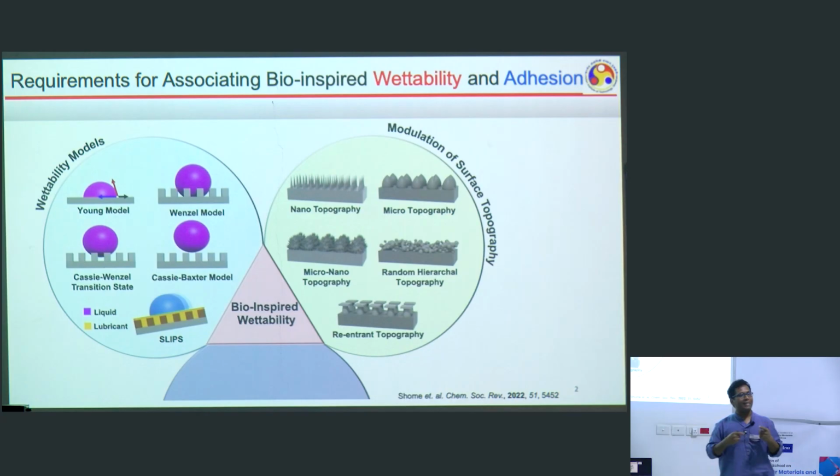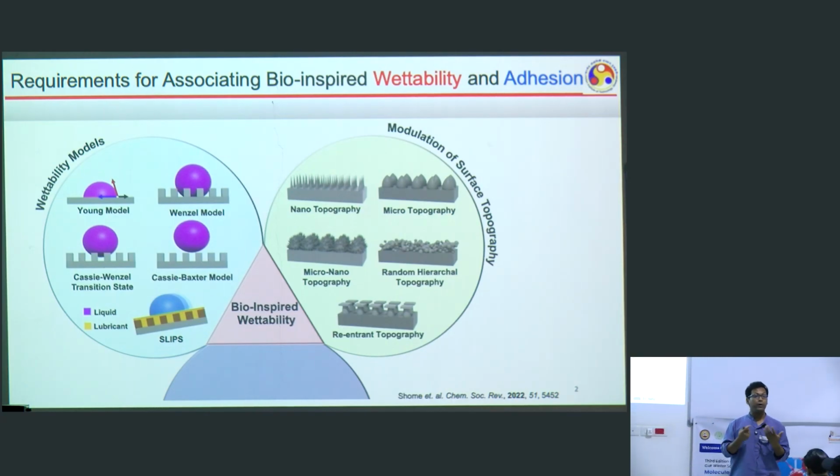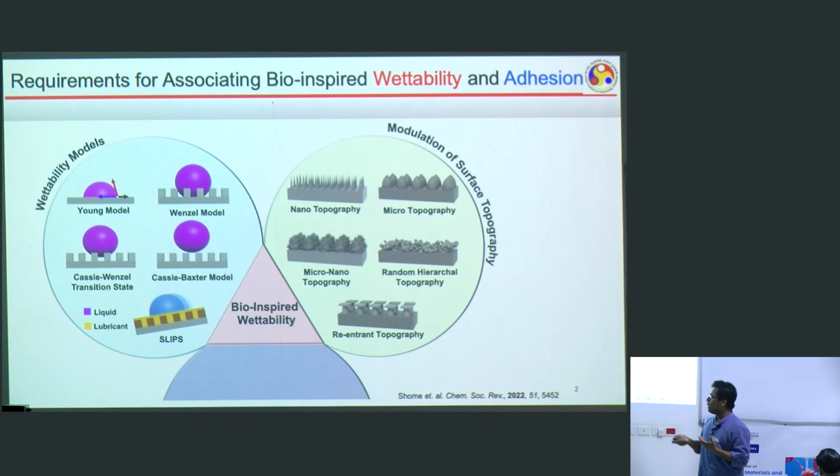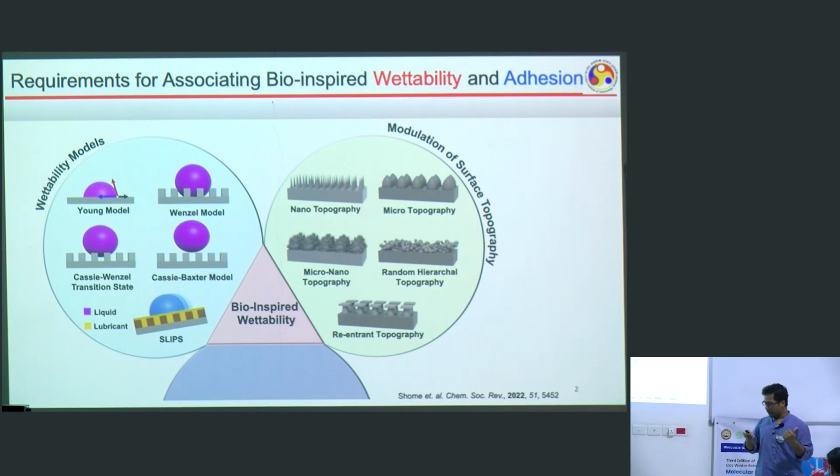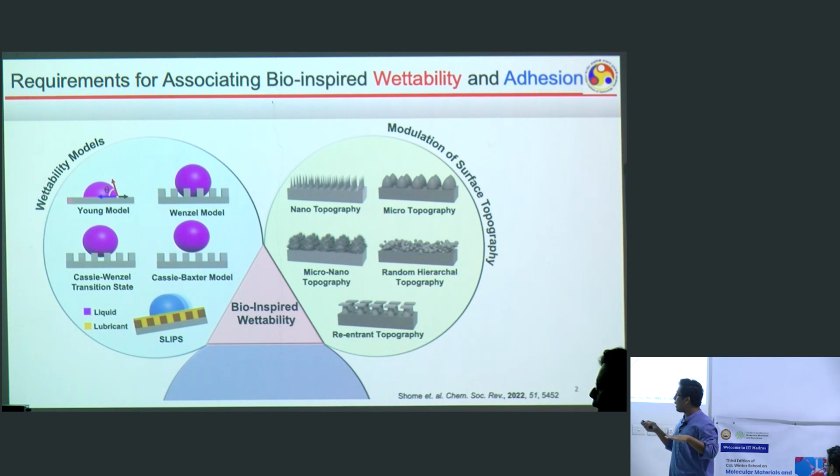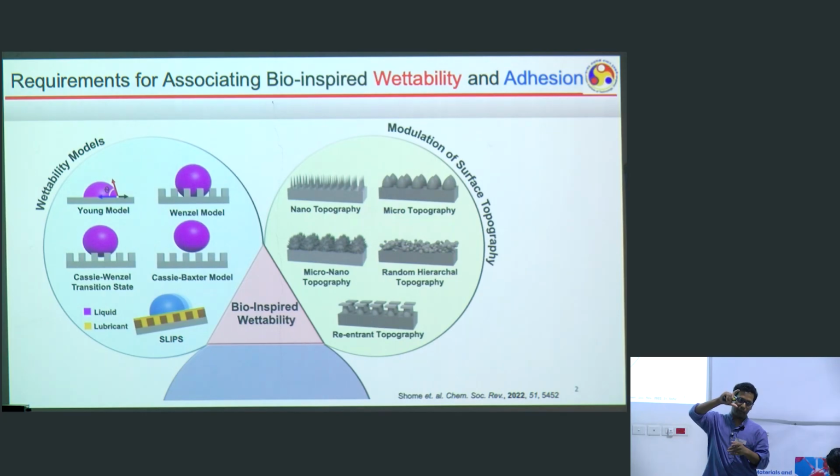Another one is basically interfacial tension, that between the liquid and the solid surface. But as they are vector quantities, they are projected in different directions, right? And what is the contact angle? If you take this particular tangent and this particular blue line, whatever angle is established, that is the contact angle. Okay. Now, when you put the water droplet on a glass substrate, initially it will be with a high contact angle, in layman's language a greater height of the droplet for a given size, and over time you will see that it's getting depleted, and then it will be stationary.